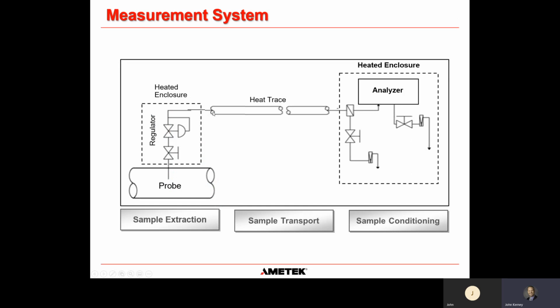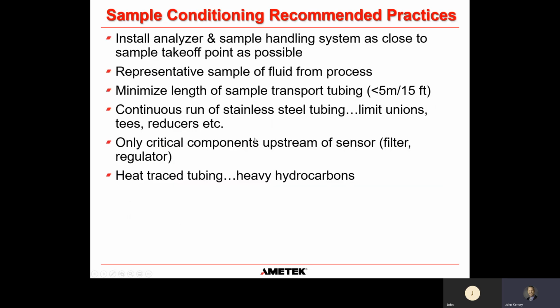Ideally, you want to have a continuous run of tubing from the sample takeoff point to the analyzer itself. And you don't want to have a lot of breaks in the tubing and connections and reconnections. All that lends itself to is leakage, potential leak sources, as well as just increasing the surface area, which is going to slow down the response of your measurement system.